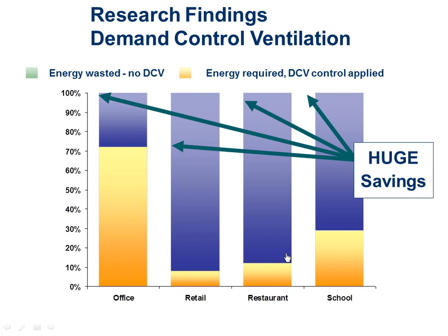If the dining room and kitchen are on their own independent pressure zones, then I can do this kind of thing. And then in schools here, you see it's a big, huge 70% reduction in outside air, which seems kind of unbelievable because hopefully your kids aren't missing 70% of the days of school. There's several things that contribute to that. One is the classroom is designed for 35 or 40 kids, but you only got 27 or 30 of them in there this year.